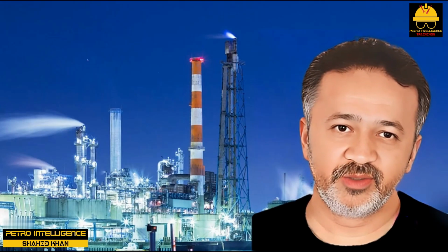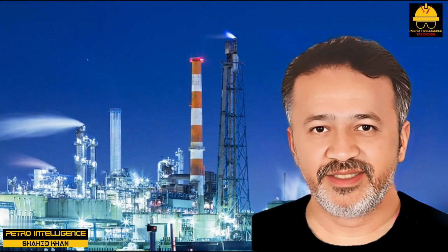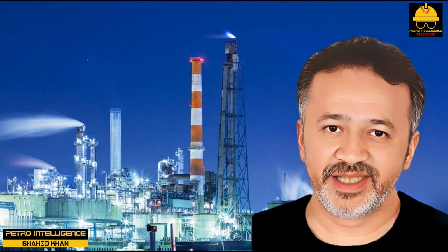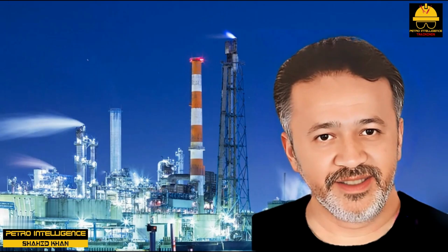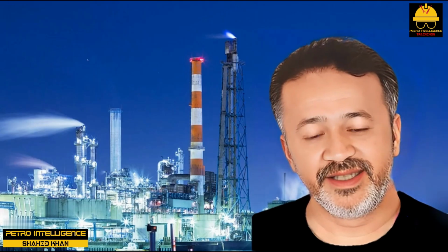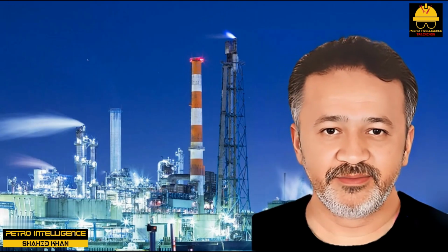If the compressor is suction volume limited, we say that it is speed limited. If the compressor is driven by an AC motor, its speed is determined by the motor speed and any connecting gears. If the compressor is driven by a turbine, then the rated speed of the turbine limits the compressor speed.